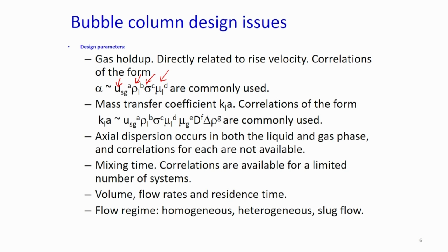Now, what do we want to measure? You want to measure KLA. This is the major problem in the bubble column: you want to maximize not only the surface area, you want to maximize KLA.